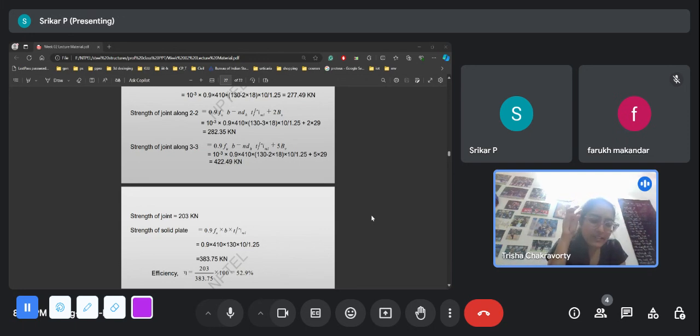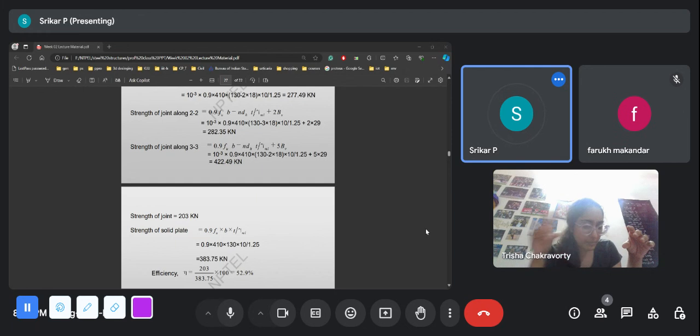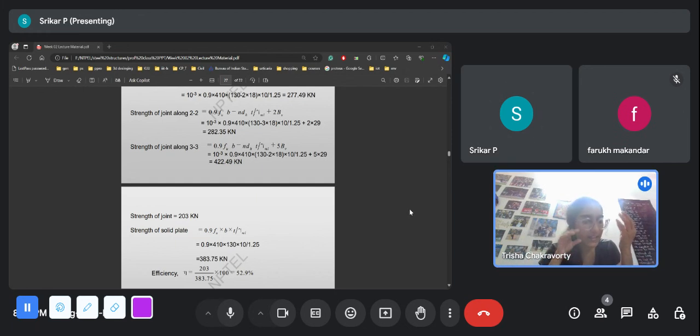When there is an assembly of structural elements collectively taking a force, one member fails, and then there is a force distribution, and the other parts have to take the entire force. What this says is that the first line of defense has given way, so the entire force has been transferred to that line. But you are saying that they have mentioned equal distribution in all the bolts, so then this argument does not hold anymore.